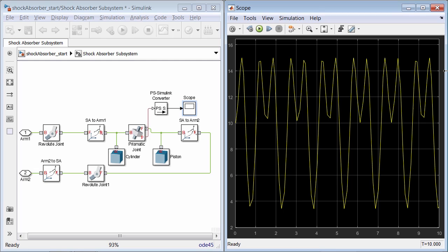So, the pendulum-like behavior is because the prismatic joint is modeled in an ideal fashion and doesn't seem to have any stiffness or damping specified. Also note that the signal looks a little jagged because we are using default solver options. If we used a different solver, for example ODE23T, we can see a smoother curve. Please refer to the documentation link in the resources section to get more information about this.